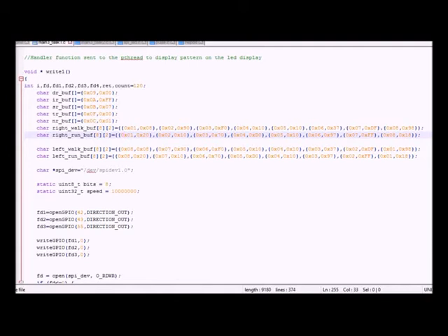Here in my assignment I have configured it in such a way that if your distance keeps decreasing as you come closer to the sensor, it moves left, and if your distance keeps increasing, it goes right. So based on the distance value, you can manipulate the time difference between each frame as well as the direction in which the dog moves. So let us look into how that is done when it is implemented on the Galileo board.